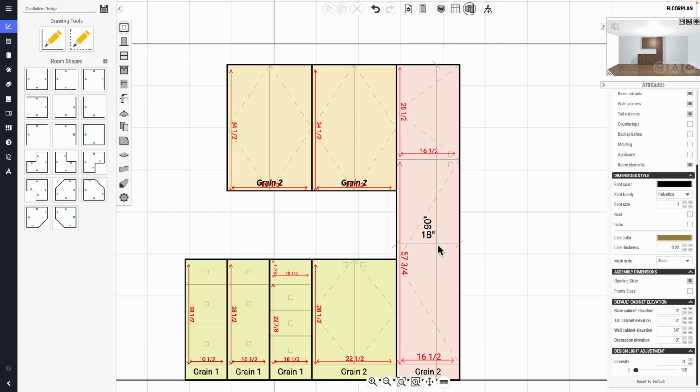Now, for frameless, this will ignore adjustable shelves, you will ignore rollout shelves, rollout trays, and closet rods. You will just consider drawer stretchers, fixed shelves, possibly simple shelves, and just sides and tops and opening case parts, so to speak. For framed cabinets, the opening sizes are just the frame opening sizes. We will ignore adjustable shelves and any other shelf that might get in the way.